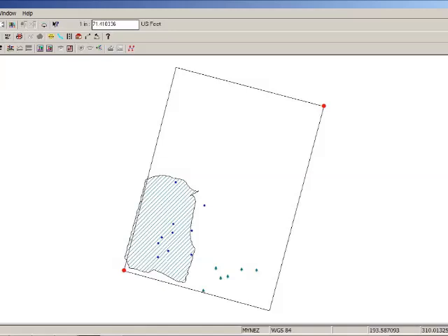To use the NEZ coordinate system that you've created in PC-GIS in your CMT-GIS app, you must copy the user_pla.sys file to the Documents folder of your app.